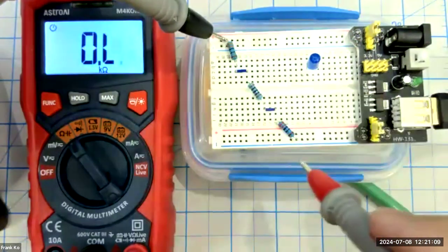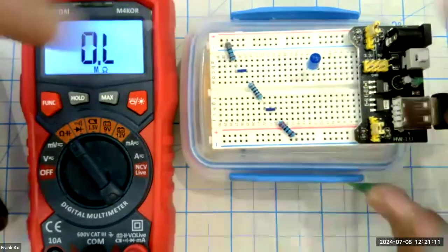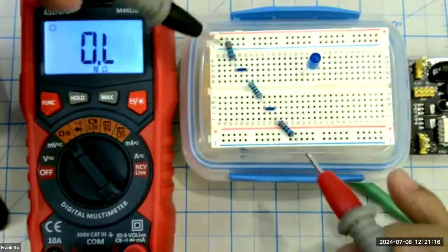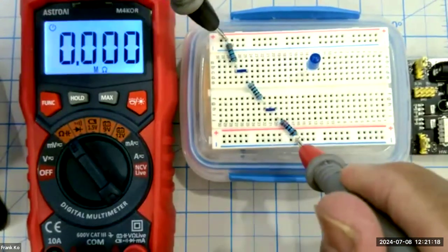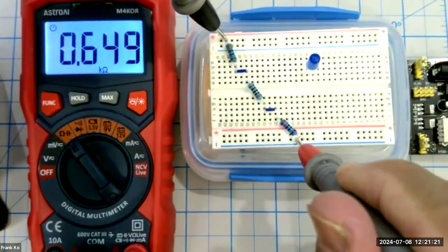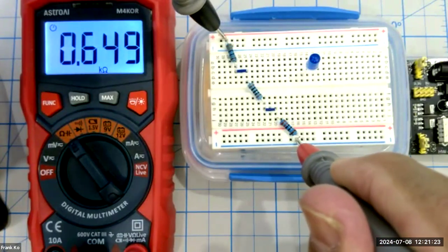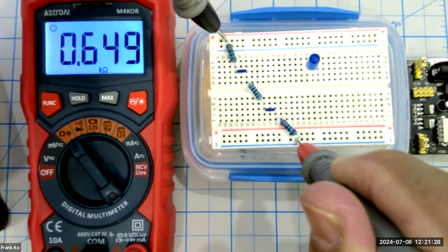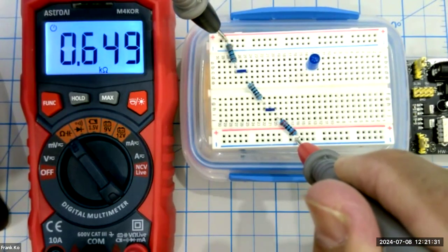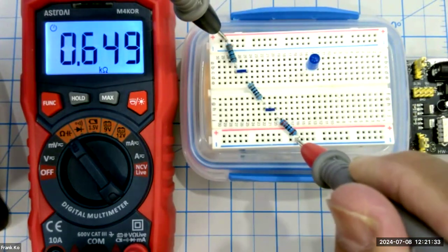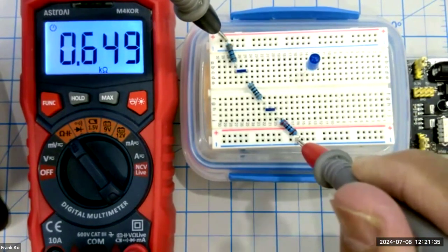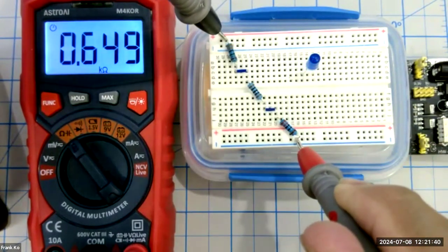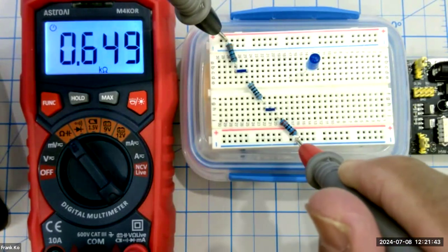If we want to leave this intact to measure total ohms, we do for a moment pull this guy off. Now it's off the board. And now if you go to hook this up here to here, ta-da, we'll get something close to our 650. And there's your 0.649 kilo. And so as another reminder, if you have a 0.649 kilo, how is 0.649 kilo 650 ohms or close to 650 ohms? Well, my friends, again, this is a review of a previous video, having to learn and understand how your calculator works and how engineering notation works.